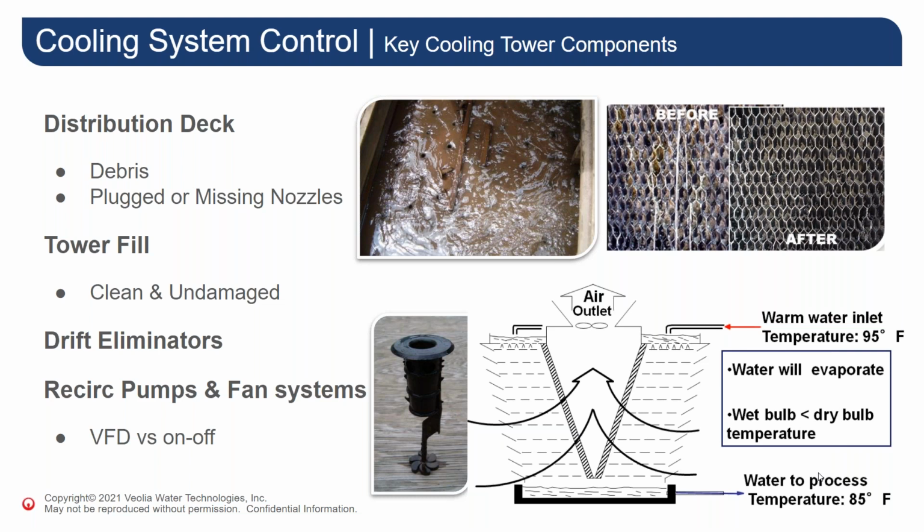The tower fill itself must be free of blockages, be it debris, ice, or anything else that would impair the ability of the air and water to flow as designed. The picture in the top right shows a fouled and a clean thin film fill, and the lower right is a general schematic showing the airflow through a typical cooling tower.